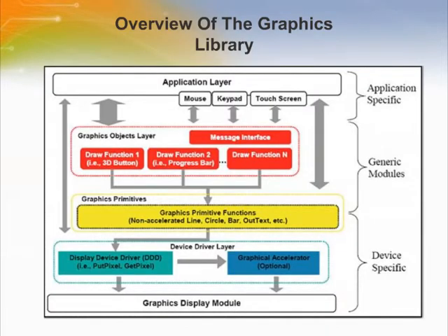The Microchip graphics library was created to cover a broad range of display device controllers. Targeted for use with the PIC microcontrollers, it offers an application programming interface that performs rendering of primitive graphic objects as well as advanced widget-like objects. The library also facilitates easy integration of input devices through a messaging interface. Applications created using the library will also find a simple and straightforward process to change display devices if the need arises. The layered architectural design of the library makes all of this possible.